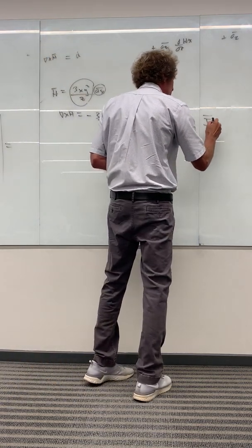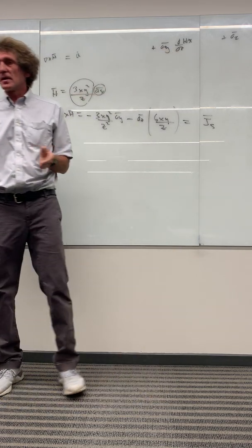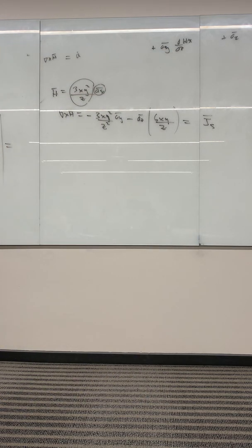So if you were asked in a problem, find the current density at a certain set of coordinates, given the H field, you'd have to take the curl of the H field and simply evaluate it there. That's the basic process. Now for cylindrical and spherical coordinates for the operations, they're given in the back. They're a little more complicated. Where's the curl? Right there.